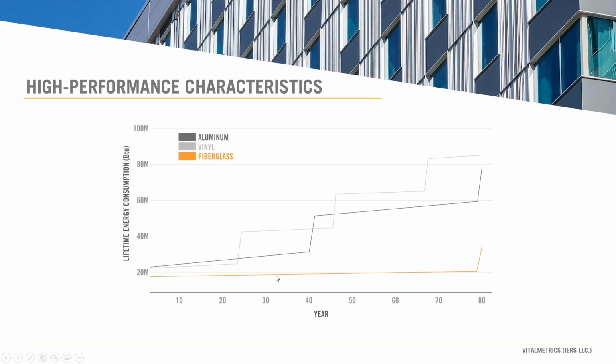The others are slightly more, but the bigger consideration is how that lifetime plays into the cost of replacing those windows repeatedly in the future, and it adds up. So there's a similar discussion to be had here around cost as well. First costs versus replacement costs, and you'll find that the durable fiberglass has significant savings in that conversation as well.